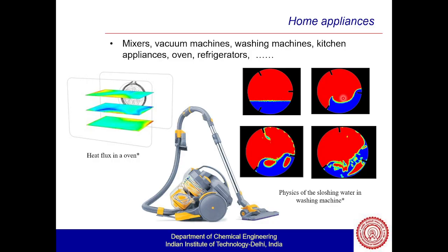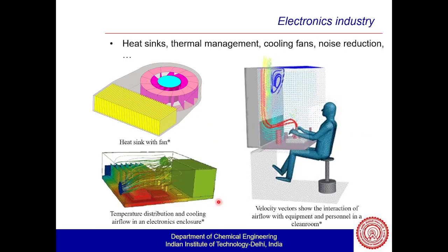So it basically depends on what your aim is, and we can also see how dust is getting sucked inside these vacuum cleaners. You're sucking the dust out of somewhere: how it gets out, how the recirculation is taking place, how much vacuum pressure is created. So you can see how the pressure gradient changes with the supplied power for a fixed configuration. This kind of thing you can see by using CFD, computational fluid dynamics.